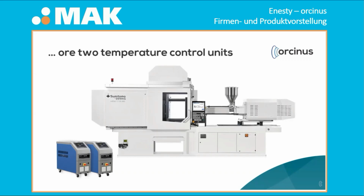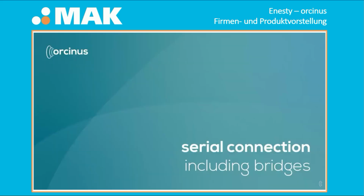But some customers do it with two TCUs because they say, I want to have one hose for the injection side and one for the moving side. But the idea is the same. The water goes inside the mold and comes out a bit warmer. So we call this a serial connection.